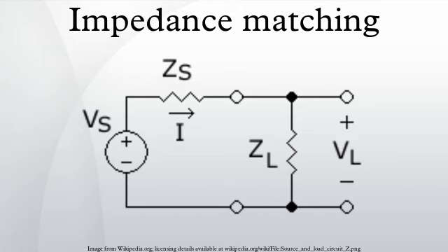Loudspeaker amplifiers. Audio amplifiers typically do not match impedances, but provide an output impedance that is lower than the load impedance, for improved speaker damping. For vacuum tube amplifiers, impedance-changing transformers are often used to get a low output impedance, and to better match the amplifier's performance to the load impedance. Some tube amplifiers have output transformer taps to adapt the amplifier output to typical loudspeaker impedances.